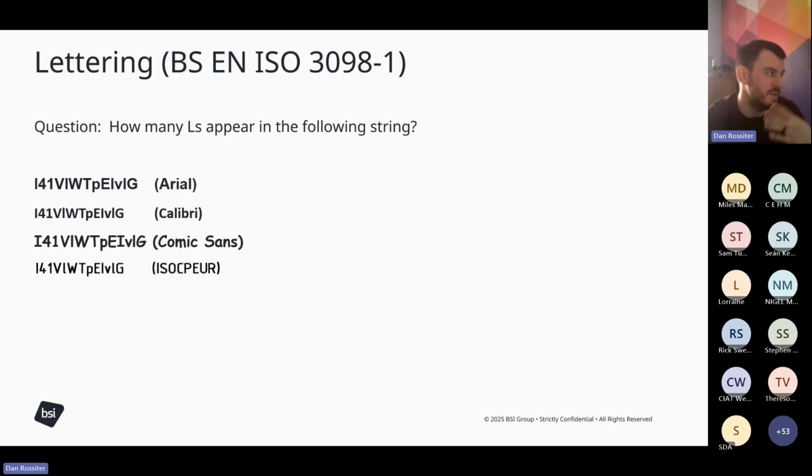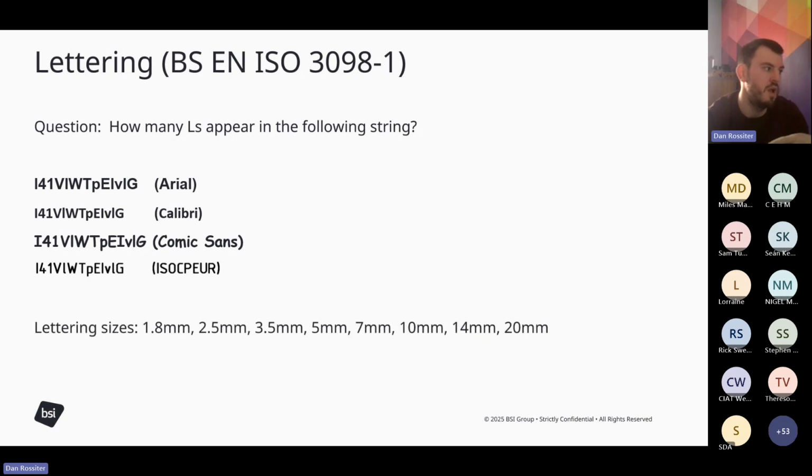And in that, it similarly has that consistency, where you can see here, for example, those L's have got a small little tail on them, so you can distinguish them from the eyes. And this sort of thing is quite important if you're writing an awful lot of specification information or your notes and annotations. When I used to do heritage drawings, we actually put a lot of the cleaning and prep work stuff on the drawing sheets themselves. And in which case, using a good, sensible font can mean that you're getting clear information across in your drawing.